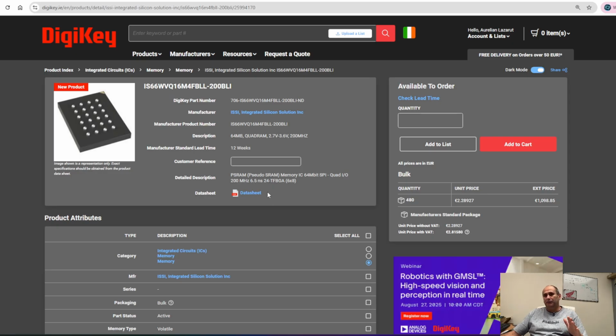Now, coming back a little bit to the name PSRAM, what PSRAM stands for. P comes from pseudo. Pseudo means not exactly that. So it's not SRAM. In SRAM the information is actually stored by transistors in flip-flops, so because of that, they can't have very large densities. This is actually, inside, dynamic RAM. It's a dynamic RAM which is seen from the outside world as SRAM, a static RAM. So that's why they put a pseudo in front, pseudo SRAM.